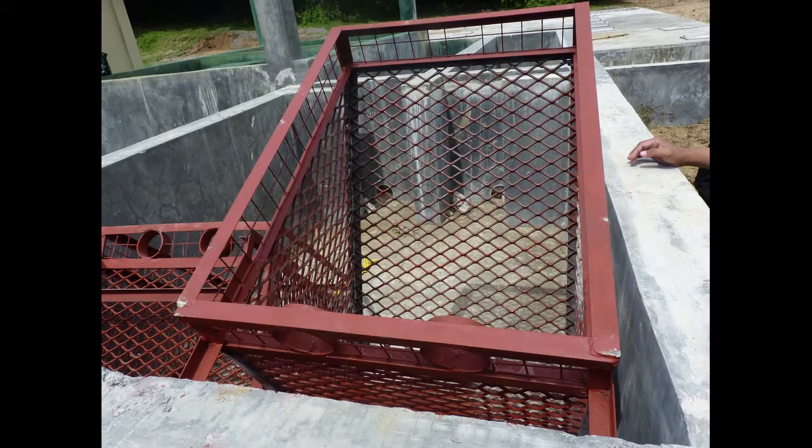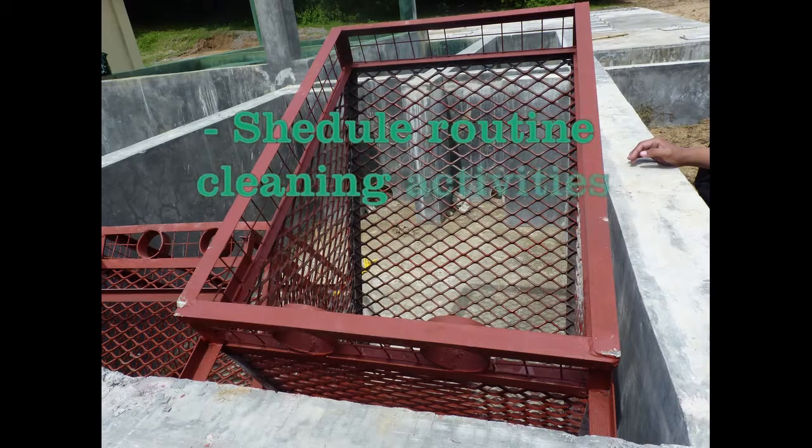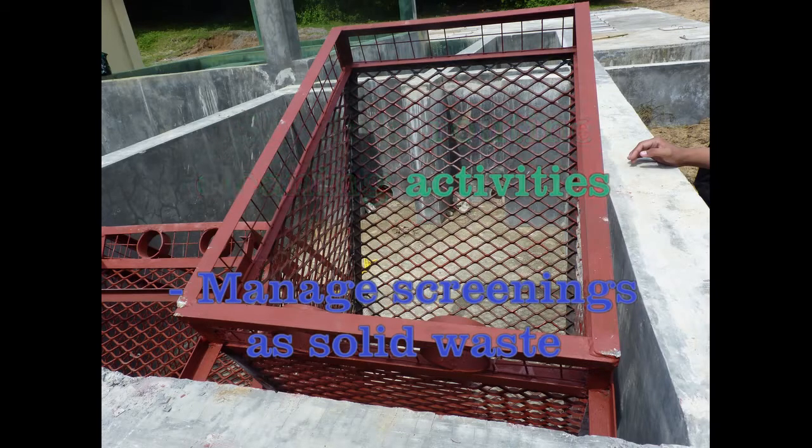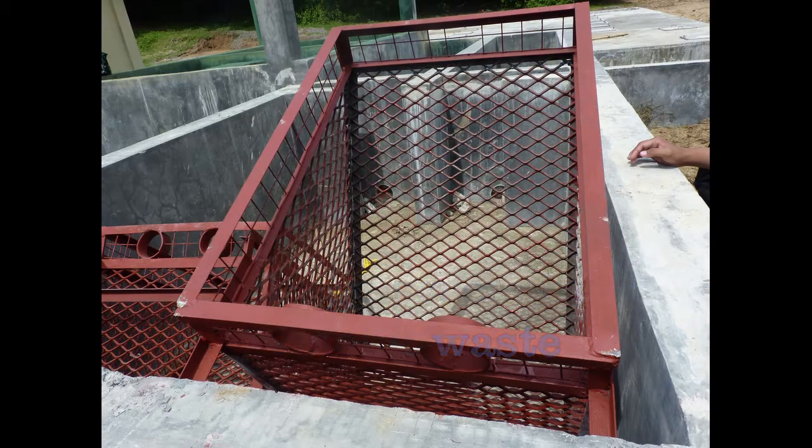This image is of a similar screening facility up in San Fernando, La Union in the northern part of the Philippines, and it illustrates how the tipping mechanism works on this screen. It's actually connected by a hinge, which makes lifting and cleaning very easy for the operators. Operators have to remember the screenings that they collect should be managed as solid waste and stored in covered containers until disposed. Routine tasks such as cleaning of screens or performing landscape maintenance is the job of the housekeeping crew.